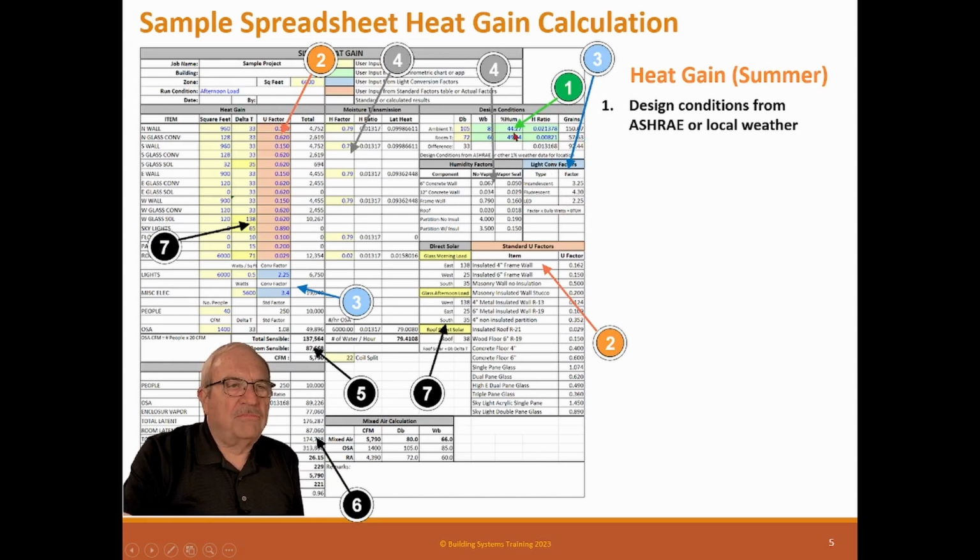So it's just 2 rows. And now this sheet you have to use, this is not smart, right? Like a computer program, it would figure it out for every hour of the day, 24 hours a day, 365 days a year to give you a heat gain. This is an instantaneous. It does it for 1.